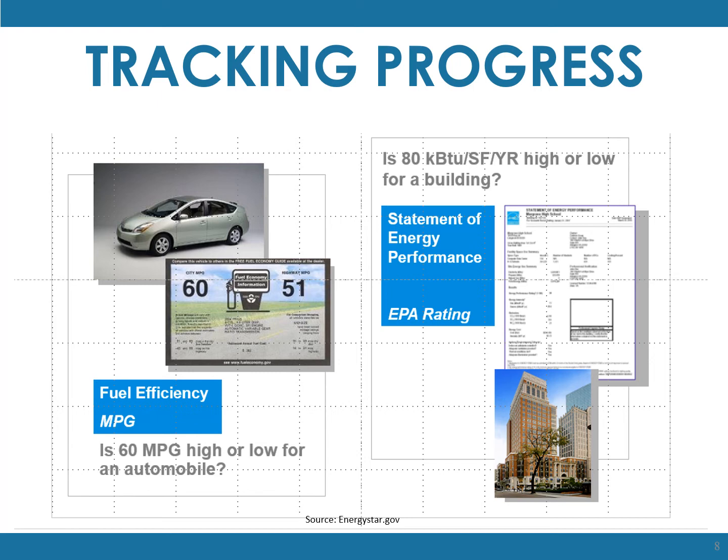Through benchmarking, real consumption data are connected with operational characteristics of a building to create comparable efficiency ratings. This is similar to a miles per gallon rating for the fuel efficiency of automobiles. Benchmarking can reveal that even buildings of a similar type consume energy in different ways, depending on use type, operations, management, and maintenance practices.